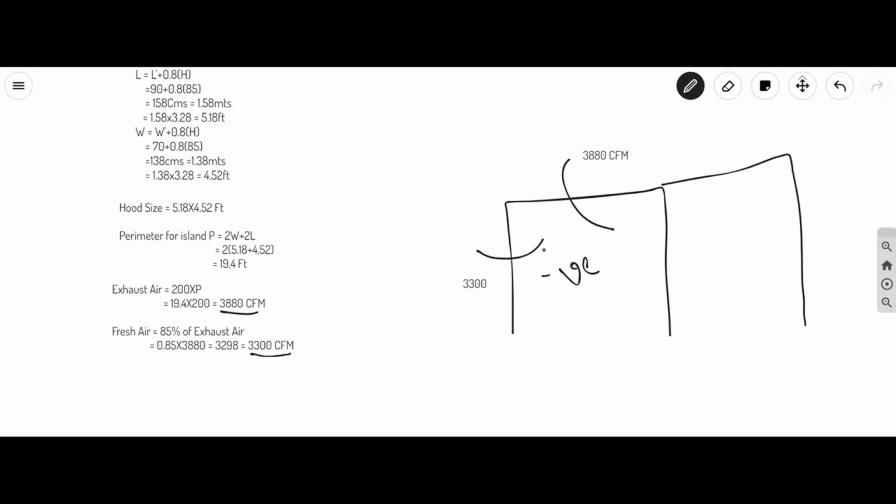if there are some rooms here, the air from the surrounding rooms will go inside it. So when you create a negative pressure, this air moves to here, so that the smoke which generates here will never be able to travel to these rooms.